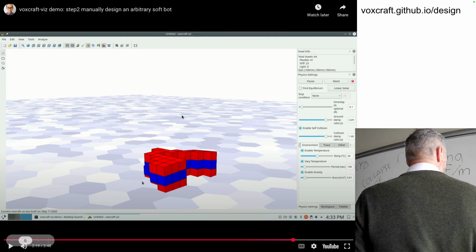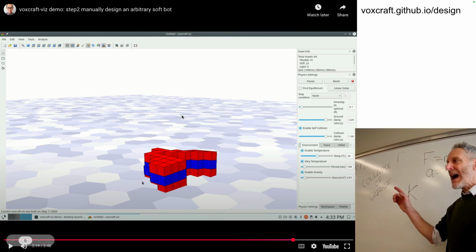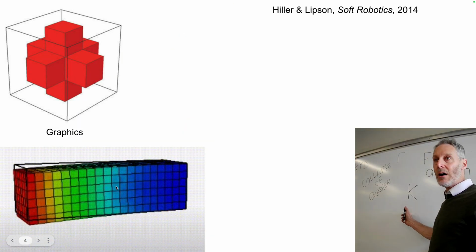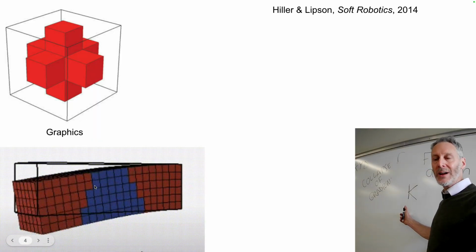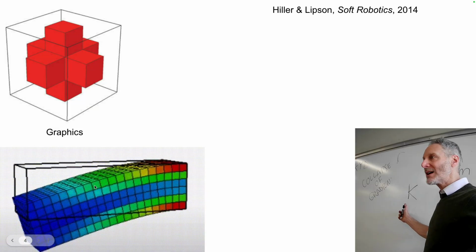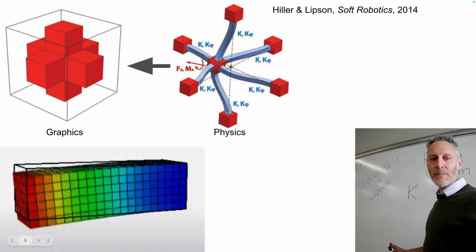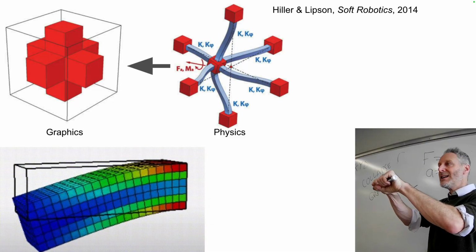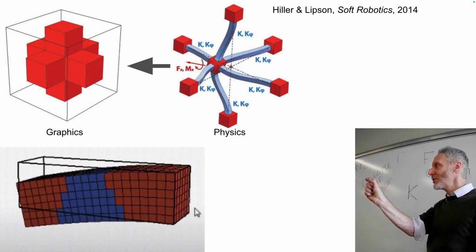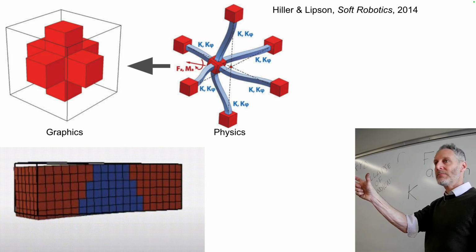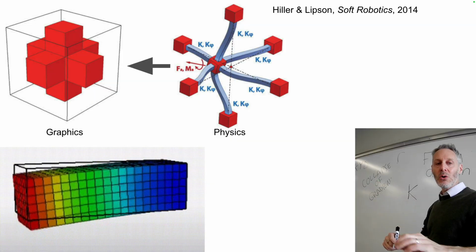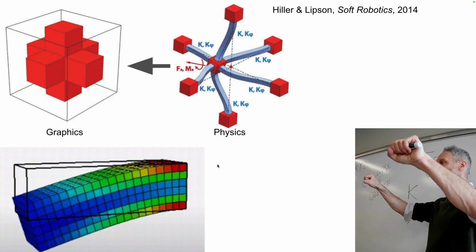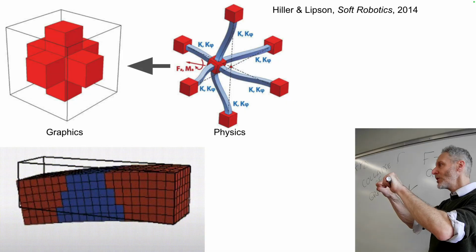So we haven't talked about the actuation. I'm going to turn the lights back on. We haven't talked about the actuation yet inside this robot. So it turns out that you can use VoxCAD to simulate inanimate objects like rubber and steel and clay. You can turn it into a robot simulator by taking all of the steel beams, or each of the beams, cutting them in half and putting an actual spring in the middle and attaching a motor to the spring, which reduces the resting length of that spring or extends that spring. You can also think about it like a piston, if you like. So we're going to actuate these materials. We're going to turn these materials into robots by increasing the length or decreasing the length of these beams, which are now springs or pistons.